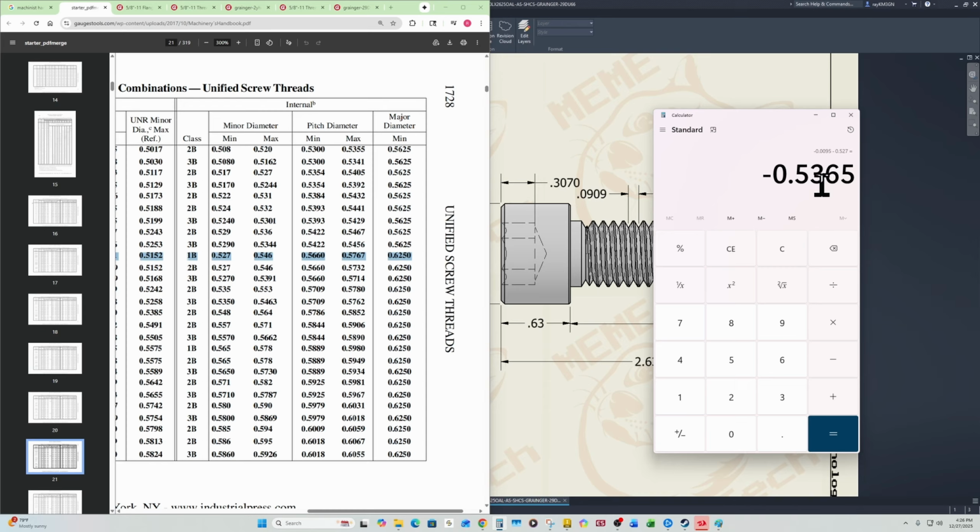You'll probably find something metric. But more than likely, the easiest thing to grab for someone in the US is probably a spade drill. At least for me, it's a spade drill here in Texas. Some people might just grab a drill. I just grab a spade drill and the spade insert, what would this be, 17/32, right? 17/32, 0.531.